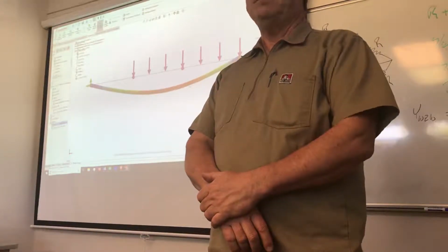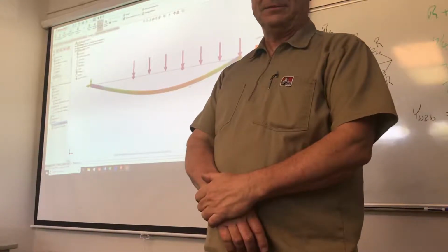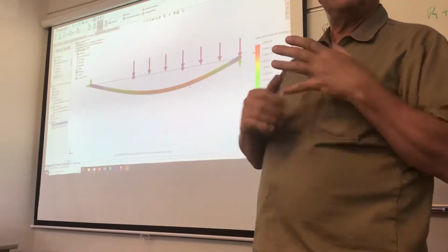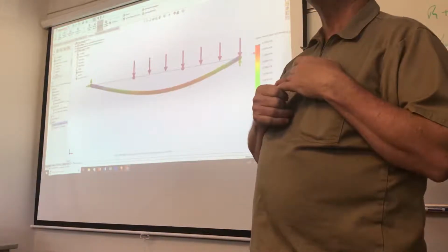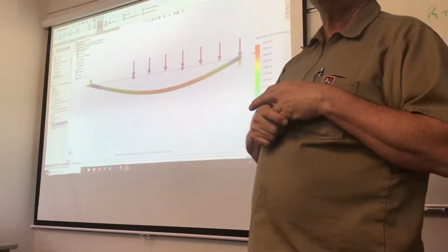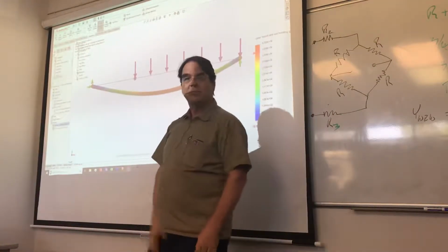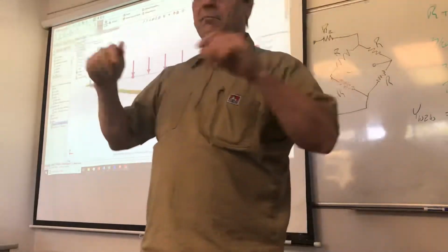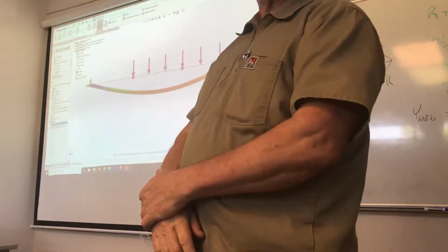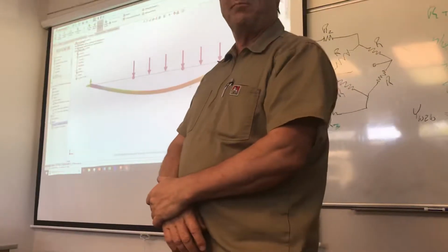It's pretty close. I'm inclined to take it real seriously, because first of all, it's over the yield strength, and not at a place where it's necessarily artificial. It's not where I'm putting the loads on, it's not where I have a constraint. It's over strength right over here in the middle, away from my displacement constraints and other things. So I'm not thinking this is an artifact of the modeling, assuming my loads were representative of what I want to park on it.